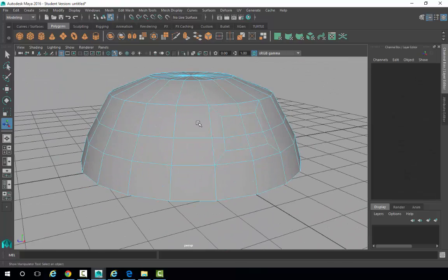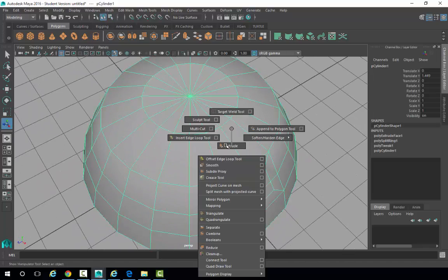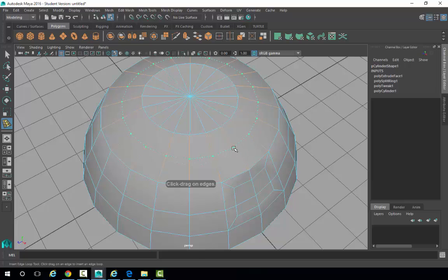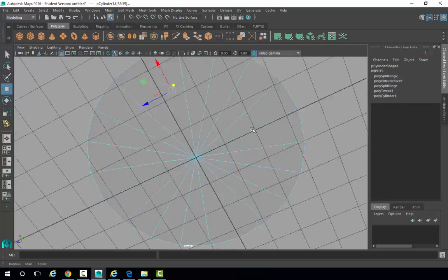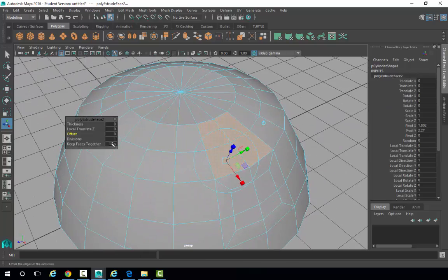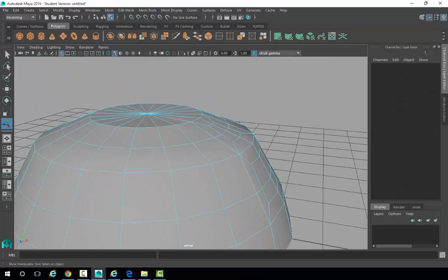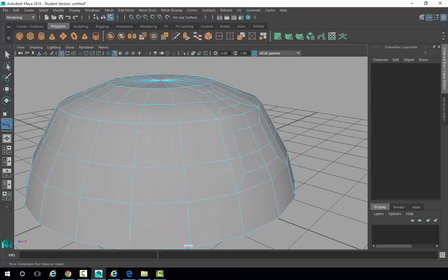And I'm going to create a cylinder for this one. So this is going to be the bottom, and then I'm going to put one up here as well. So this is going to go in there, and I'm going to put one in there, just making sure I don't select anything else. So I'm going to use the extrude face, and again using the middle mouse I'm just going to offset that as well. So this is creating the area where I'm going to put my 2 handle pieces.